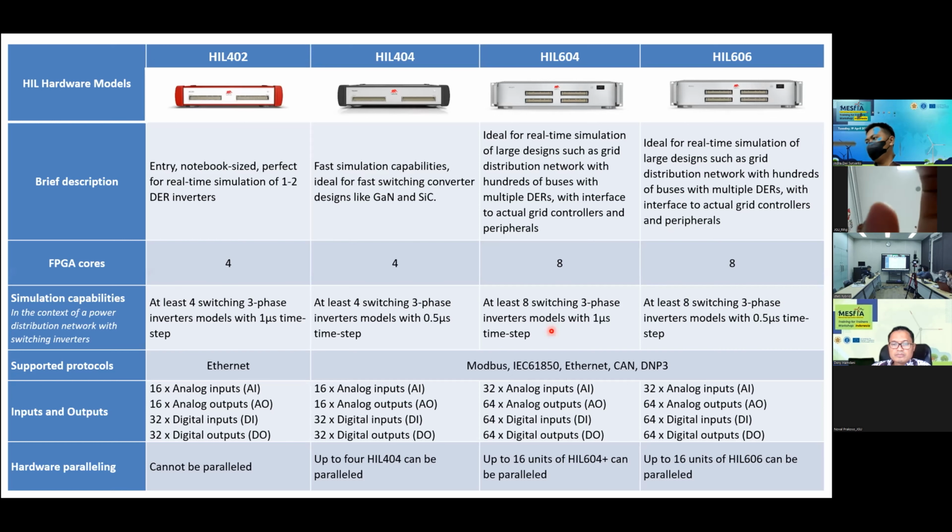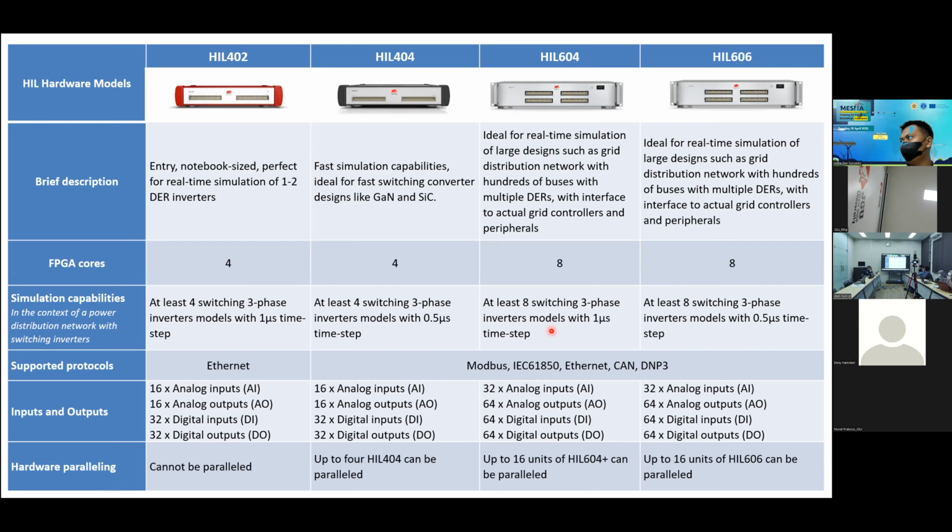The microgrid could have PV, wind, diesel genset, BESS, and each of them has a three-phase inverter in it. You can test eight of those in parallel, so you can form an entire microgrid system and see how it works. Later we will look into it in greater detail.